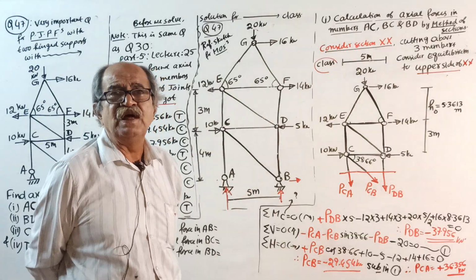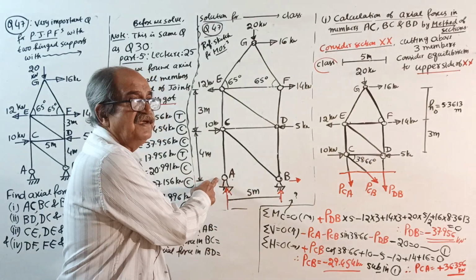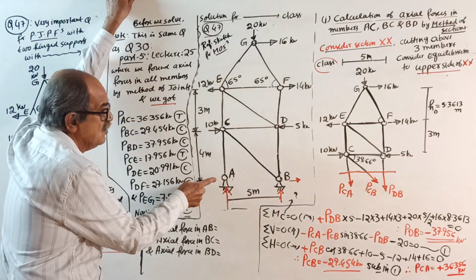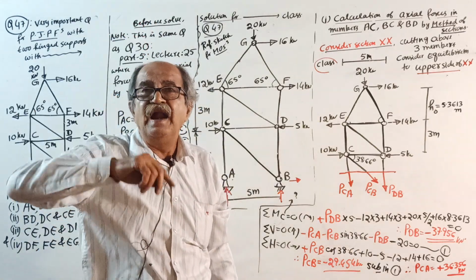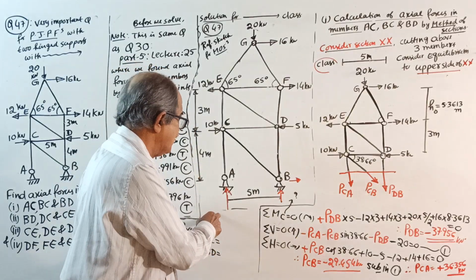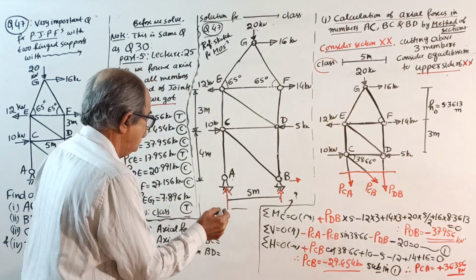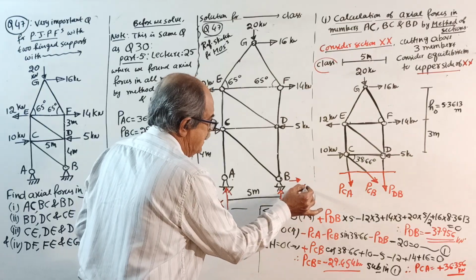Then we can write a roller there. You don't write that way. A hinge is a hinge. See this hinge, horizontal reaction is possible, but here it is not possible. Earlier I told this, and also told you how to find the reaction for those who are eager. Therefore, don't find this reaction. Do not find it.